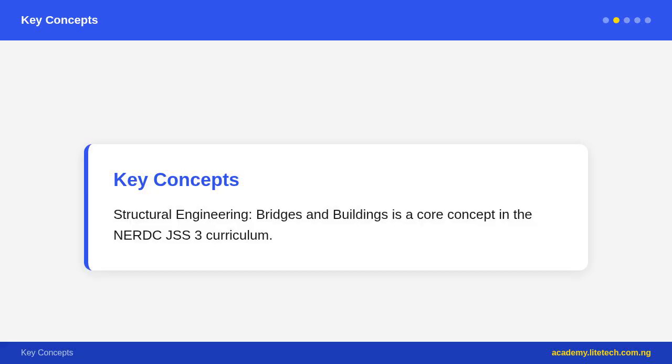4. Suspension bridge, the bridge deck hangs from cables that are slung over tall towers and anchored to the ground at each end. Cables carry the load in tension. Very economical for very long spans. Example: Golden Gate Bridge, San Francisco.